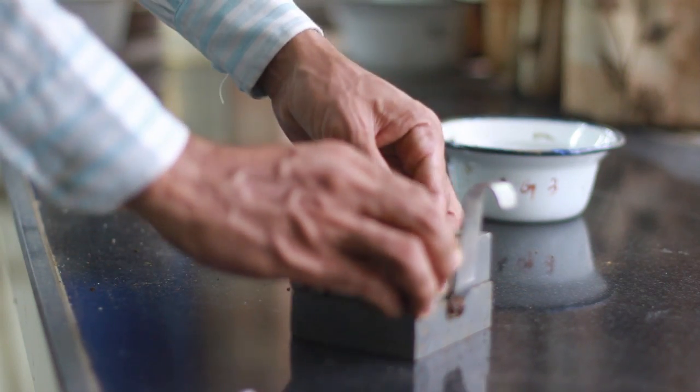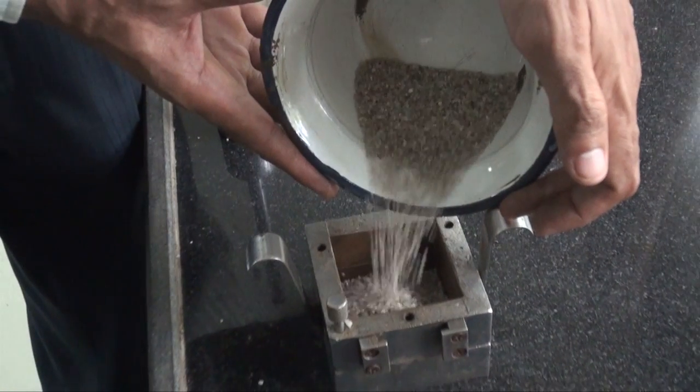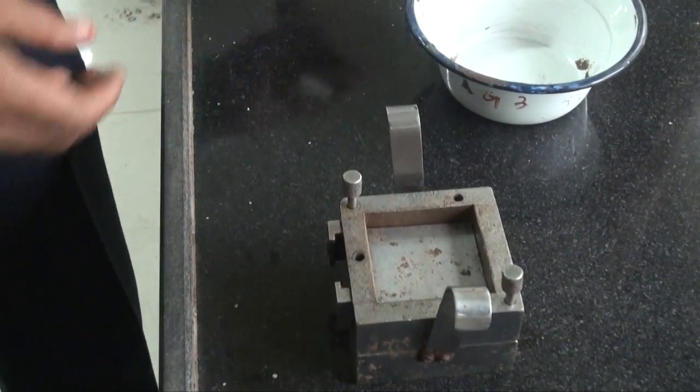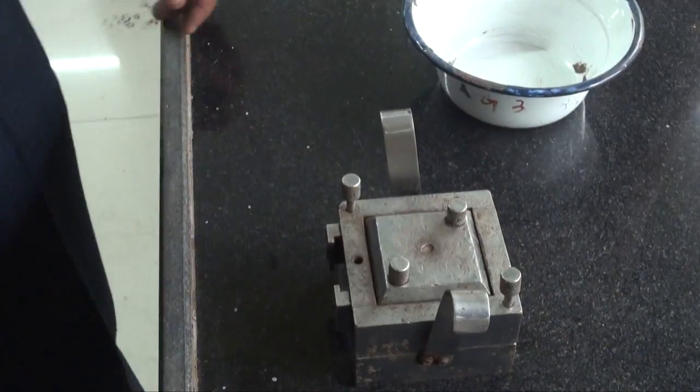Moving on to the direct shear test. Well, it is an easy test to determine the shear capacity of the soil. Soil is filled in a box called the shear box, which is split into two halves along the middle. Initially, the two halves of the box are held together by locking pins, and during the test, the pins are removed